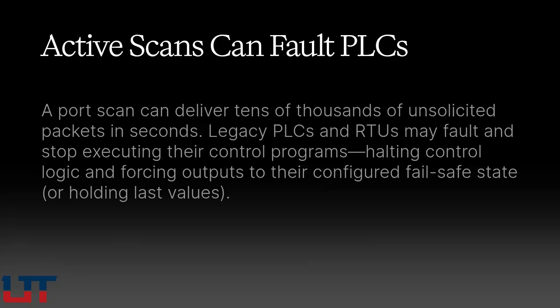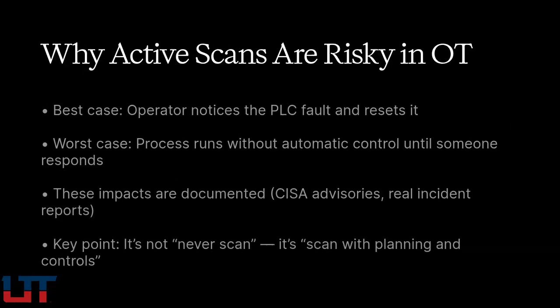Legacy PLCs and RTUs receiving that kind of traffic have been observed to fault and stop executing their control programs. The control application halts. The outputs go to their configured fail-safe states or hold their last values. In a best case, an operator notices the PLC has faulted and manually resets it. In a worst case, the process continues without automatic control until someone responds. Again, this has been documented in CISA advisories and in post-incident reports from real industrial facilities. The message is not never scan OT networks. The message is never scan OT networks without understanding what you're scanning, with a maintenance window and a recovery plan in place.